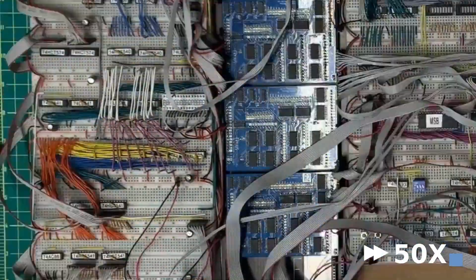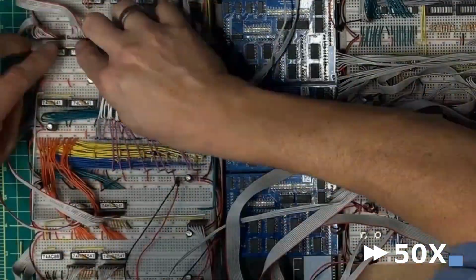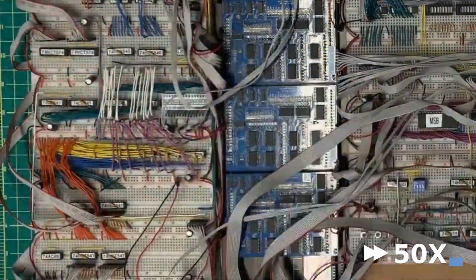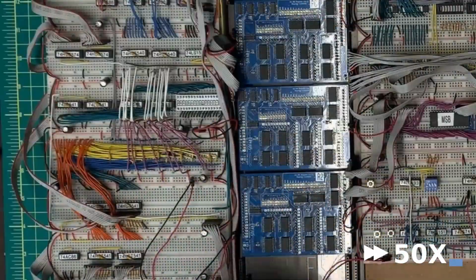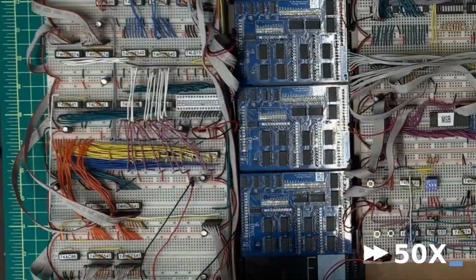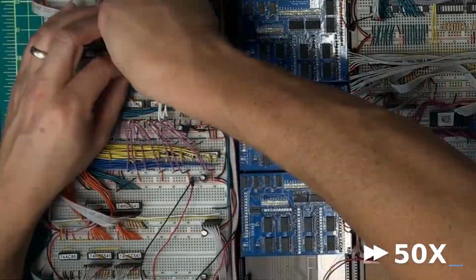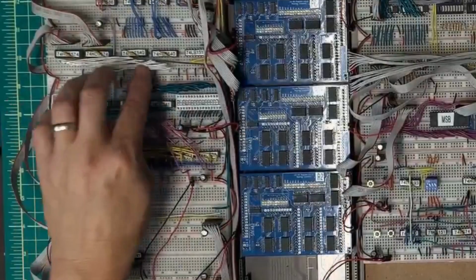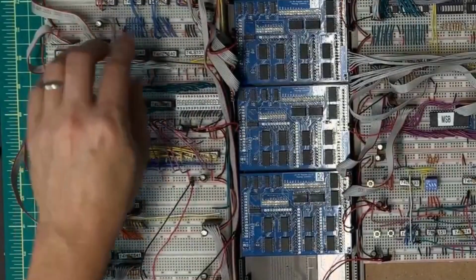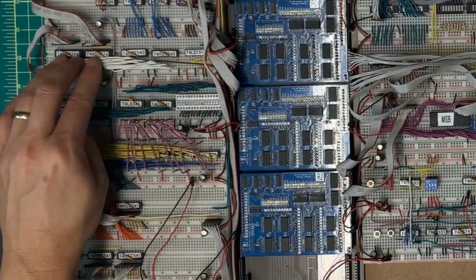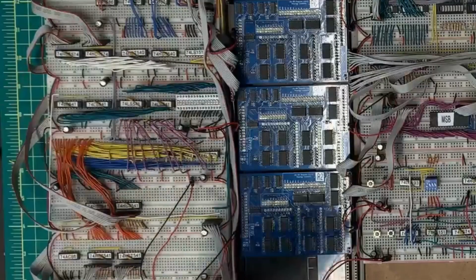Okay, power, ground, decoupling. I tie together the signals I need for latch and output enable, and then I move over the inputs into the Z flag calculation. Okay, this takes care of the zero flag calculation. That's going to come directly off this ALU bus.